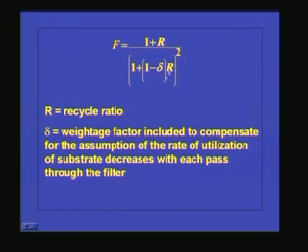So what does this delta mean? That means in the first cycle of the wastewater flow, what will happen? The organic matter will be penetrating through the biofilm and the microorganisms will be utilizing the organic matter, but the utilization rate will be depending upon the biodegradability of the waste.